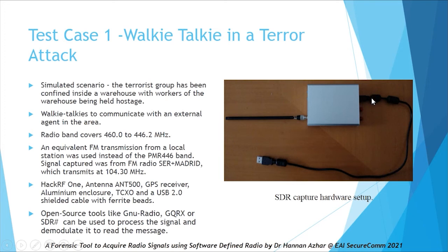We can see that this is an example of before the capture. It shows what the current setting is, and then you start setting the frequency 104.30 megahertz, and then sample rate, bandwidth, and so on. GPS, set GPS true here, and then you see this has been set up, and the results have been shown, and then you start capturing, and it shows the recording and the specific frequency and time, and that shows the successful recording of the data.